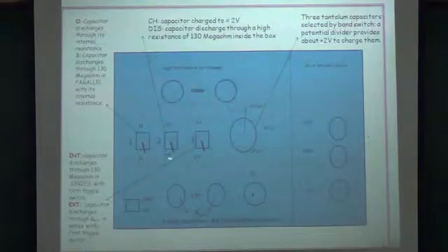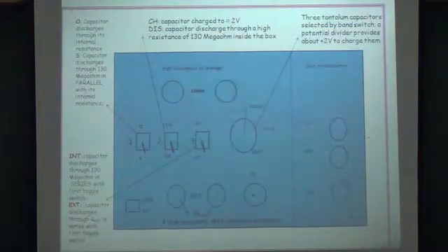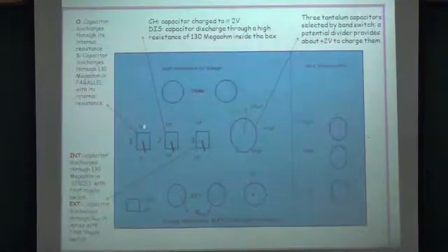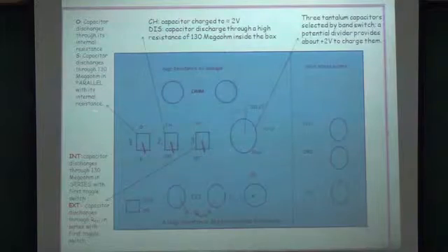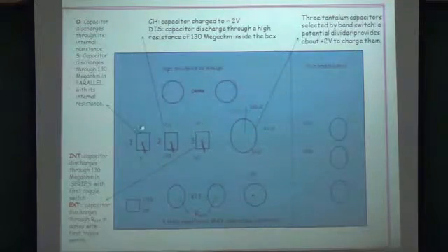This knob here is, if you put it up, you are charging the capacitor. If you put it down, you are discharging the capacitor. This O and S, if you put it in O mode, then the capacitor will discharge because of its own resistance. But if you put it down to S, that means this internal resistance here is coming in parallel to the capacitance.